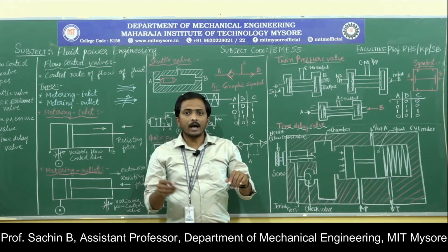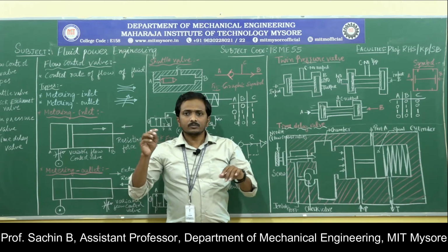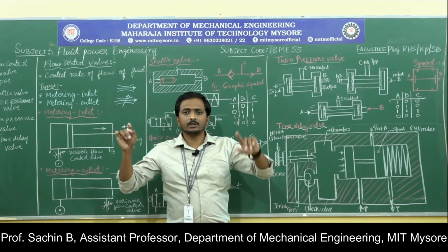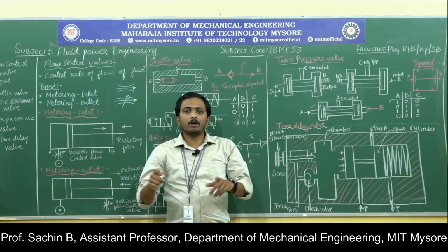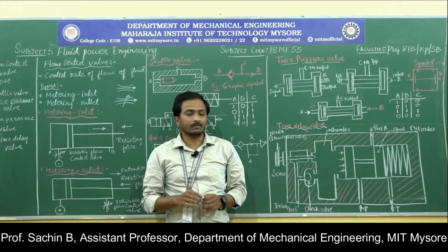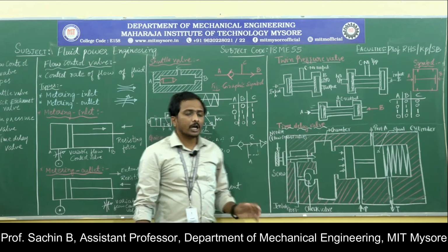The operator will not have to move the material. We are removing the operator's hands by automating it using twin pressure valves. If at a time I press the push button, both operations are possible in one cycle itself. That is why we are using the twin pressure valve. And the last one is the time delay valve.